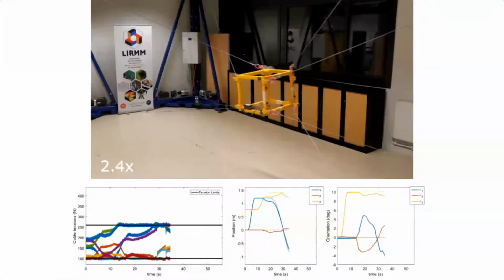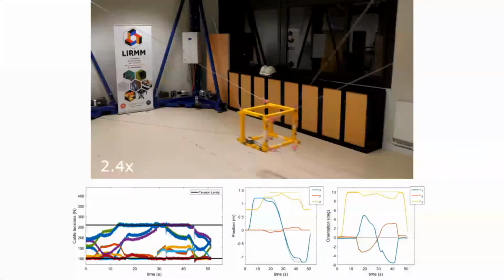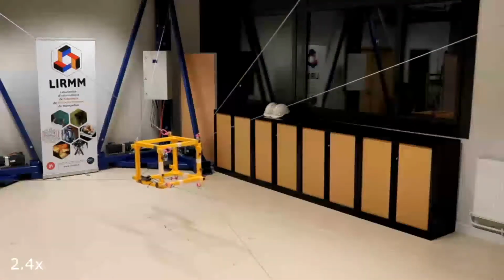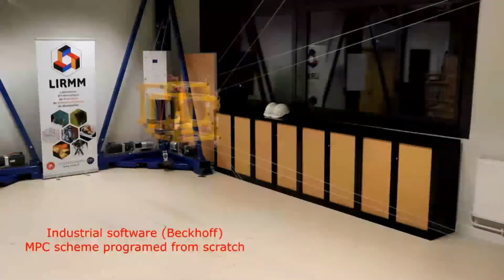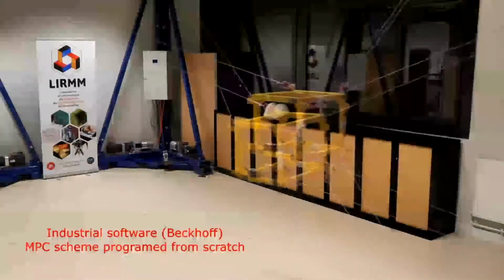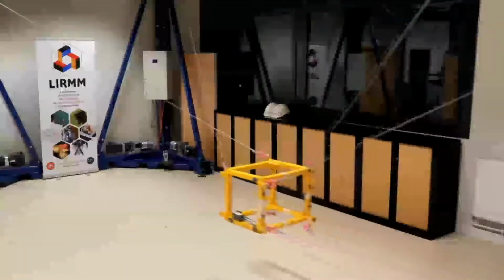Even so, the proposed MPC is able to track a trajectory as close as possible to the desired one without violating the cable tension limits. It is interesting to compare these two scenarios simultaneously. Here, I remind that the control scheme has been implemented in the industrial software TwinCAT. Since this software is not compatible with commonly used mathematical libraries, the control scheme has been implemented from scratch.